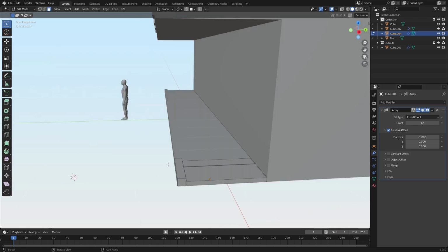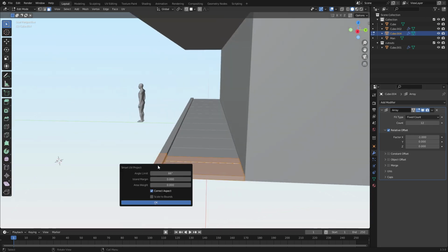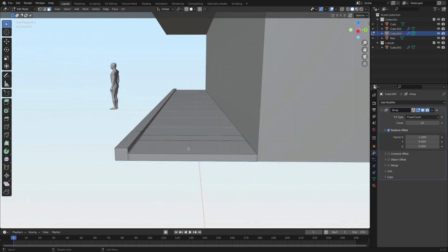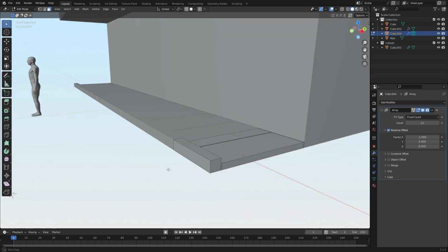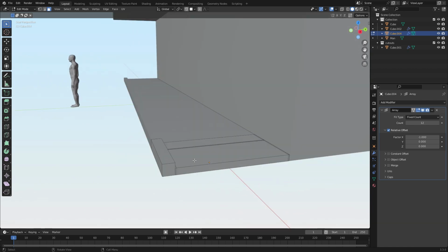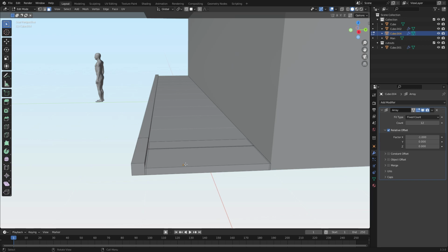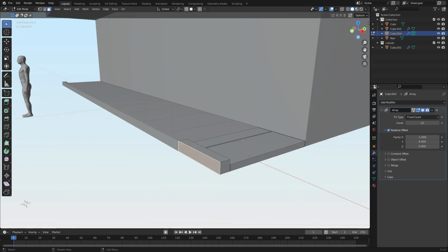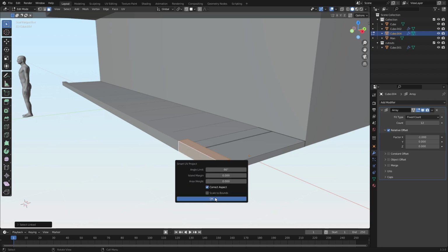Now, if you try to UV project a bunch of different meshes, it's going to give some odd results, so it's better to do them separately. I don't know if there's an add-on or something that can do them separately if you select all of them. But just hover over one of them and then hit L and then U, Smart UV Project. I just like to click on here so that it deselects that one, and then L, U, Smart UV Project.